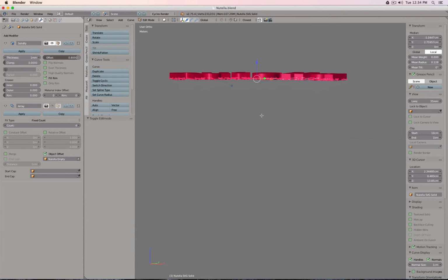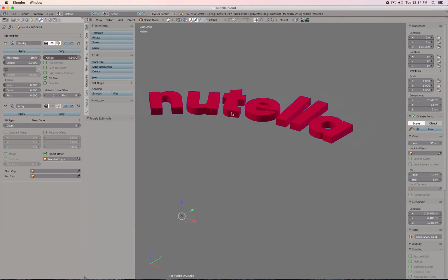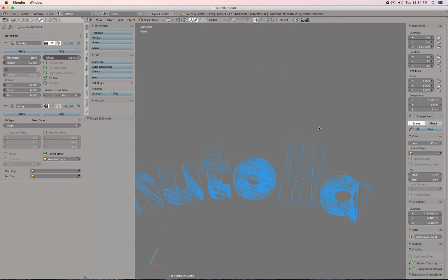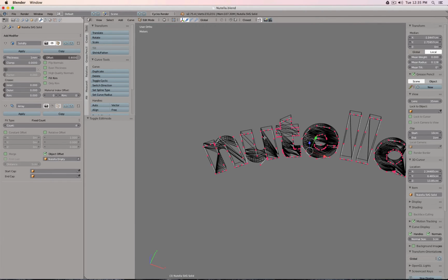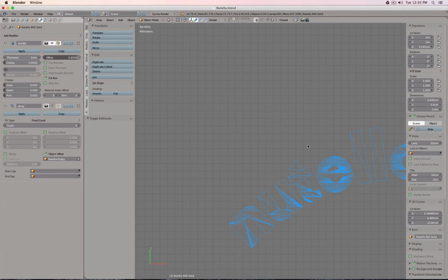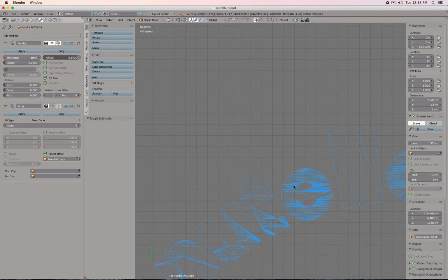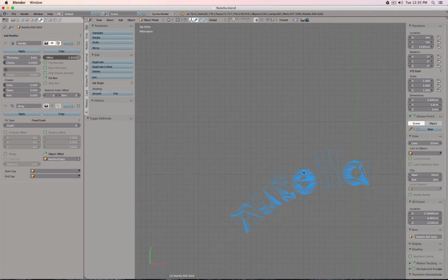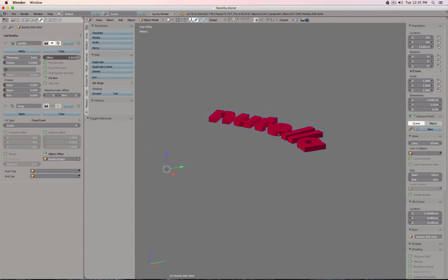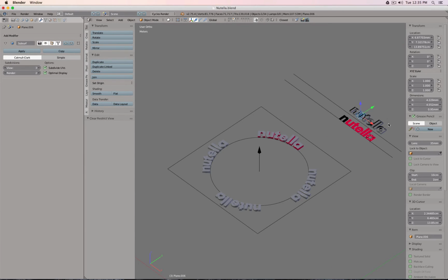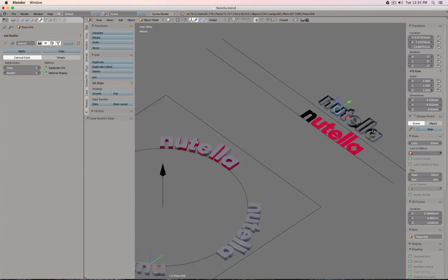So you see there's the flat SVG, but we can't really do much more with the top. And in addition, that's the bad part of Blender: when we use a curve as an input, as a surface, and then extrude it, you see it creates this kind of polygon mesh. So it makes things more dense and complicated and less efficient, and prone maybe to some hiccups or annoyances. Which is why this process has certain advantages.